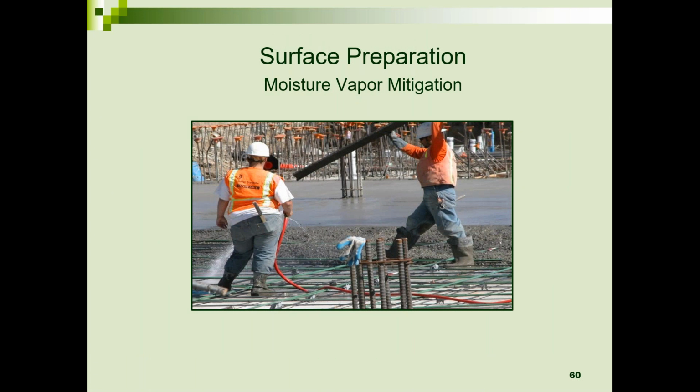Moisture. Moisture in a concrete slab comes from different sources. Obviously, there's water mixed into the ready mix for workability, placement, and cement chemistry or hydration. But water might be inadvertently added during installation, where here we see the contractor is spraying down the substrate, trying to, let's say, lubricate that surface so all that ready-mix concrete can flow under, over, and around that steel or rebar. So the contractor is incorrectly adding more moisture to that slab that eventually is going to have to leave, which can impact your flooring installation.